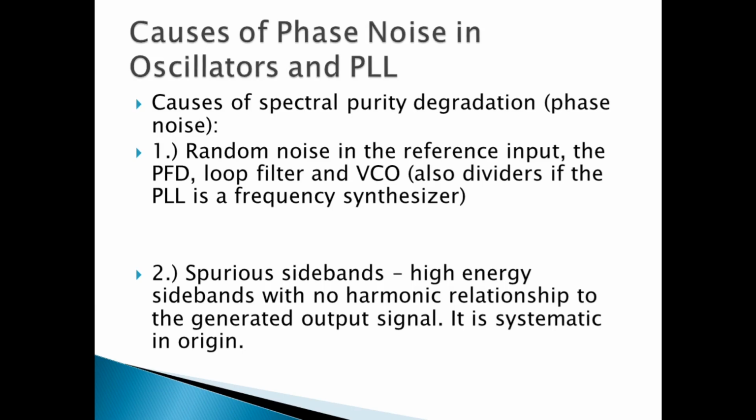Not just that, we do not have idealistic responses of systems, and you have seen in the DDS where there are some spurious sidebands which are present in the real world scenario, which are not thought of in the ideal response, but they do exist and they have absolutely no harmonic relationship and they create noise. They are responsible for adding noise in the system.